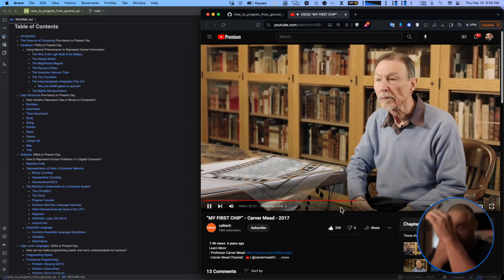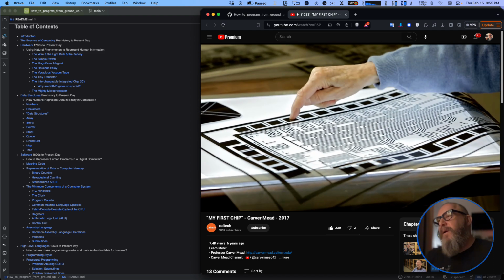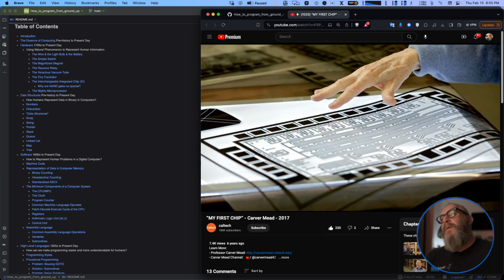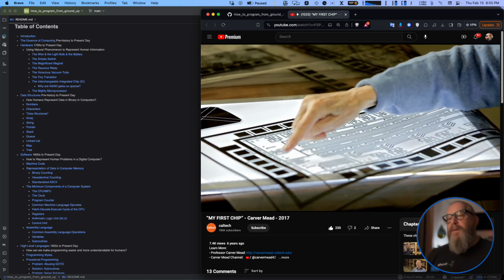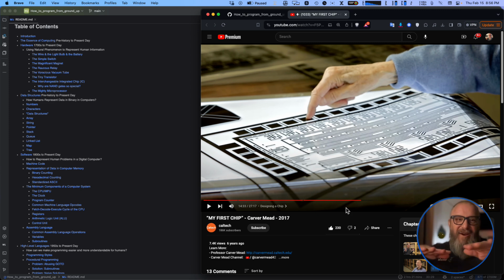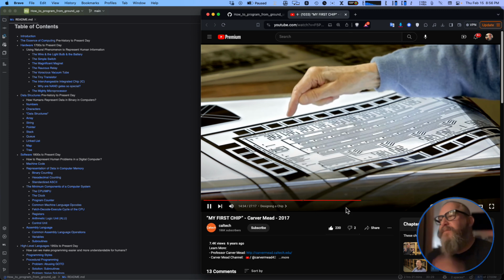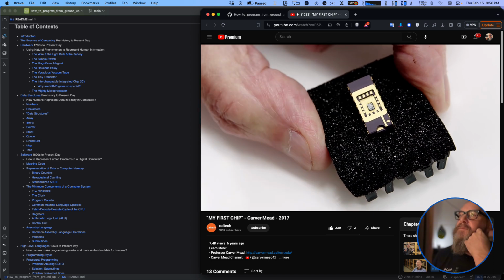So this is what came out of the Gerber plotter that we would give paper tape to. These are the contact pads. This is a metal layer, the blue one, and you can tell a lot from just looking at it. There's VDD, the power supply, and ground, and then these are the drivers that are going to drive the pads. This is just one layer of a multi-layer operation. The pads are what you make contact to with a wire that goes off inside of a package, which are the things you see that have integrated circuits in them.